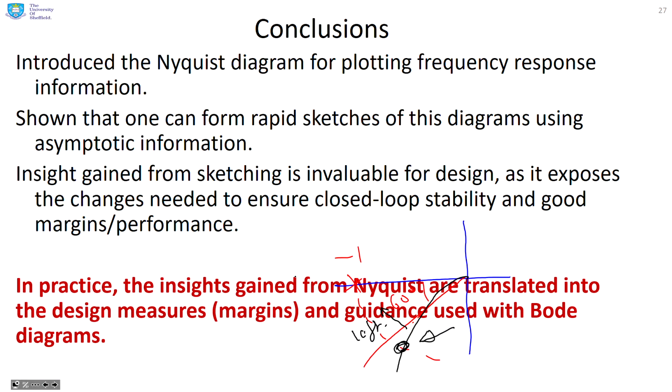Now in practice, what people tend to use is Bode diagrams. So they say Nyquist has given us the insight into what's going on. Now that I've got the insight, it's actually far easier to do the design solely using the Bode diagrams, which is what we did in the previous video.